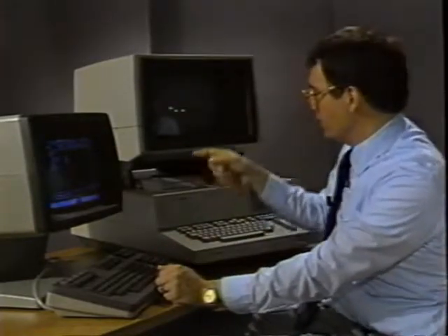Notice that we created one cylinder, rotated that cylinder, defined the angle between each cylinder, and defined the number of copies, in this case 12. This is a shaded display of those cylinders that we will subtract from the disc. This will form our flange.